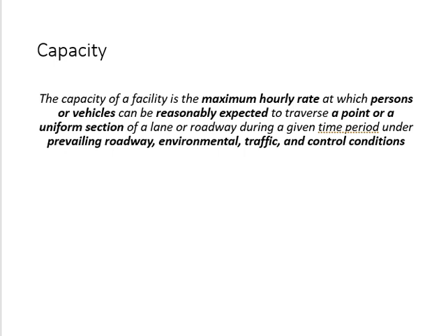According to the manual, capacity is defined as the maximum hourly rate. We called it earlier the flow rate. So capacity, according to them, is not volume, it's not flow, it's flow rate. What do we mean by flow rate? 15 minutes converted to an hour. So the maximum of that value, the value which we also use in the peak hour factor.